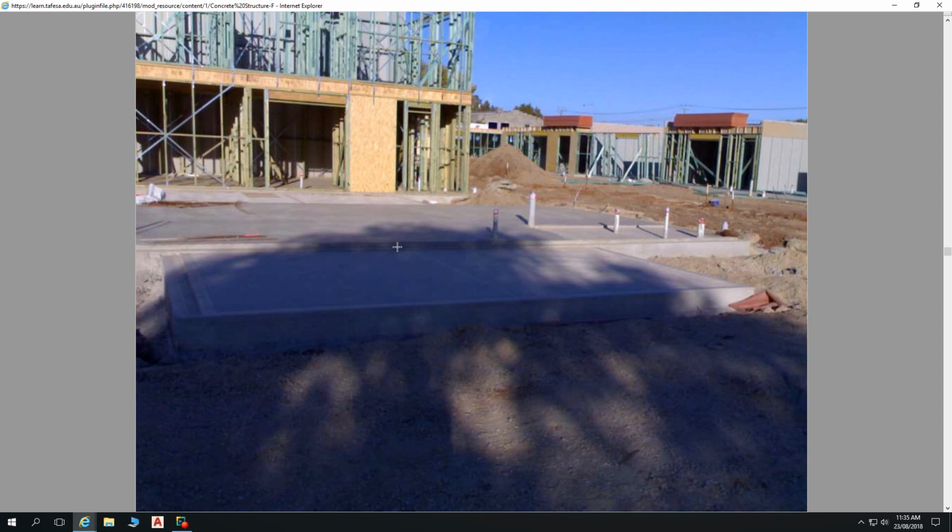Just some interesting things to see in the background. There we've got some OSB sheet bracing to help stabilise that frame. We've got some, what do we call it, engineered floor trusses there, and we'll get onto all that sort of stuff later. Some blue timber here, so that's been H2 treated for termites, and some of them are treated for fungi as well. Strap bracing happening here, so type D strap bracing to resist that.